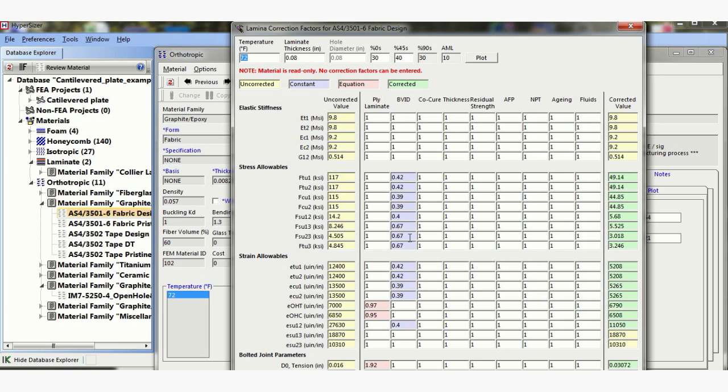You can see here a big correction, 60% reduction. Now there's an irony here in the fact that we're applying corrections to a layer, effectively a layer, not really a laminate, but unfortunately this is the way the analysis is set up. This is what most corporations do. So barely visible impact damage, you must correct your stresses and strains. You notice that the stiffness has not been corrected. On a global perspective, really the stiffness is not really corrected.